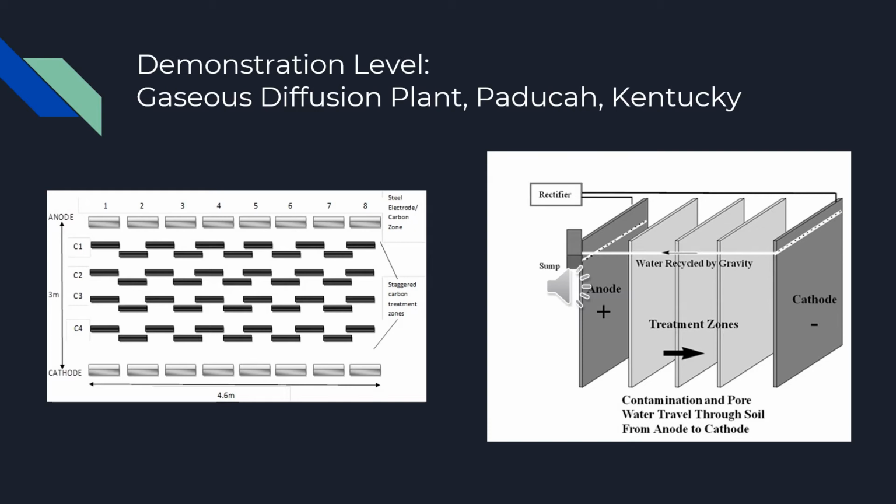Remediation. The site consisted of 4 feet of gravel and clay layers over 40 feet of sandy clay loam with inter-bedded sand layers. The hydraulic conductivity of the sandy clay was about 10 to the minus 7 centimeters per second. The test area consisted of 150 square feet for a depth of 15 feet. Average contaminant concentration was 83.2 parts per million.